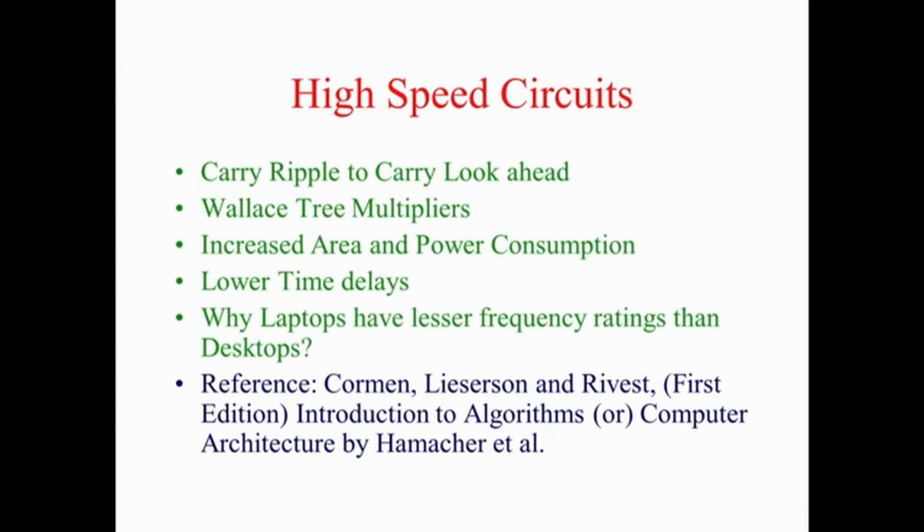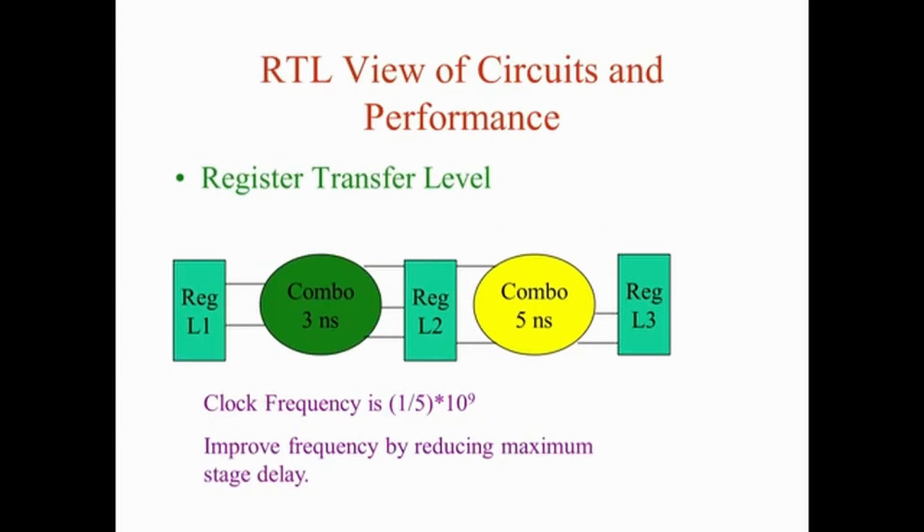So what we have done so far is we have learned what pipelining is, and there is a need for storage between two parts of the circuit to create isolation, so the data can flow from one end to another. We model the entire operation at the register transfer level, wherein the data moves from one register to the next register in different clock pulses.